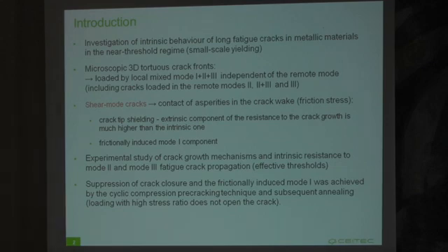At the beginning, I'd like to say that the crack fronts are microscopically tortuous, and they are loaded by a local mixed mode 1+2+3, which is also true for the pure Mode 2 and Mode 3 cracks. Dealing with shear mode cracks, there are some difficulties because we have the interaction of fracture surfaces. So we have a high amount of crack tip shielding, as well as induction of additional Mode 1 loading of the crack tip. And we are interested in the intrinsic behavior and measurement of the effective thresholds.